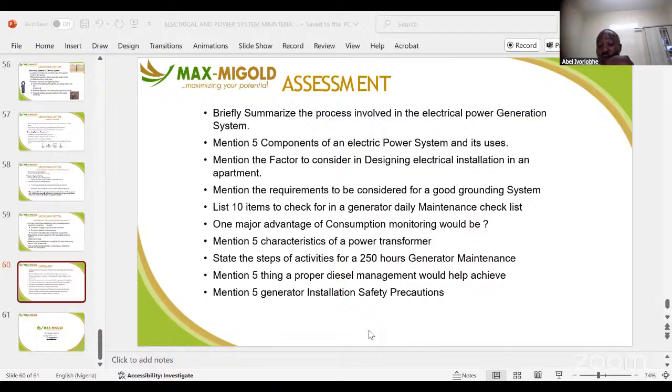What you need to do to determine the size of a generator, like I explained to them, is divide that 60 by 0.8. 0.8 is the power factor. That 60 is your real power. We don't make use of real power in electricity. We make use of apparent power. Your apparent power now is kVA.